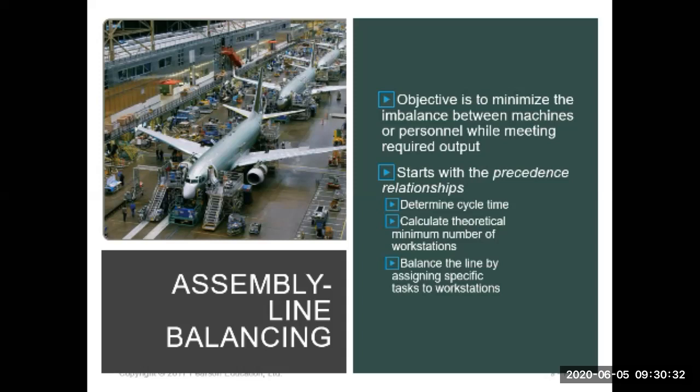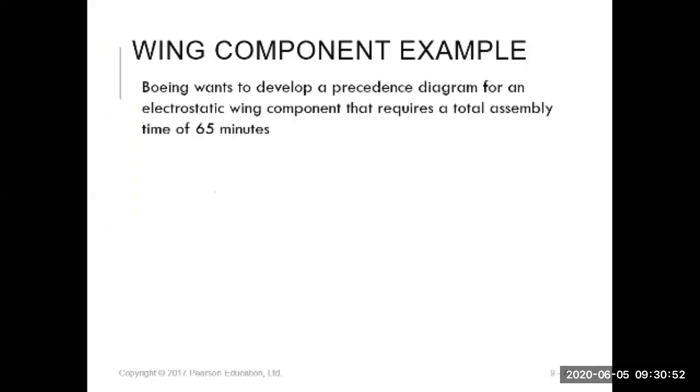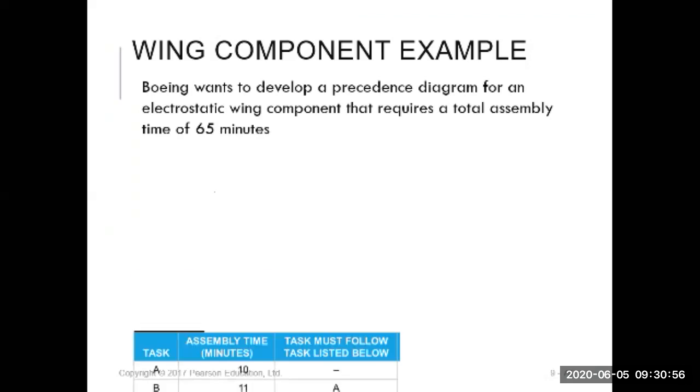We can determine the cycle time to complete the task for each unit in each workstation, then we can identify the number of workstations, and then we can assign the tasks to each workstation. So this is an example.